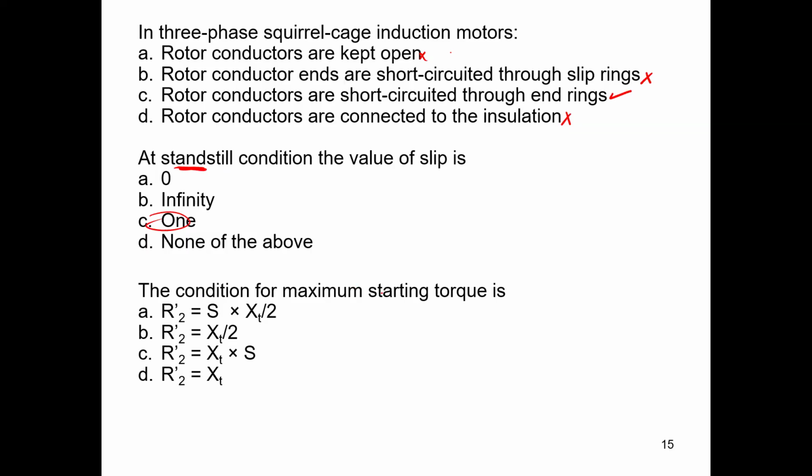The condition of maximum starting torque. You know starting torque is at S equals 1. Maximum starting torque means I need to move this curve here. This can be done, guys, by speed control or controlling the machine.